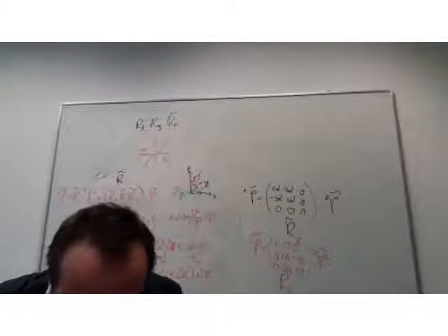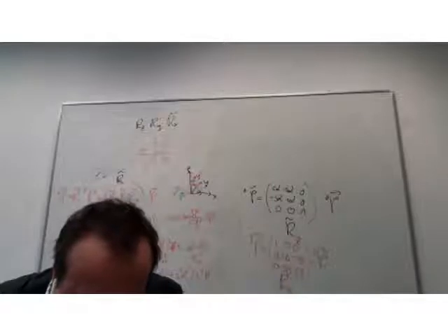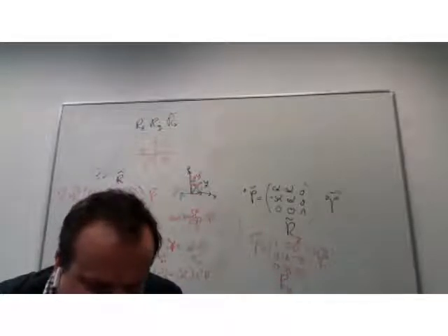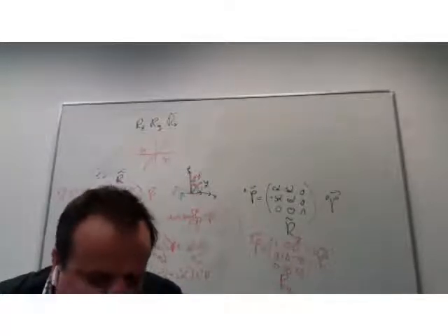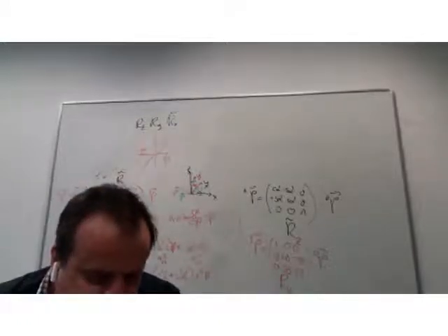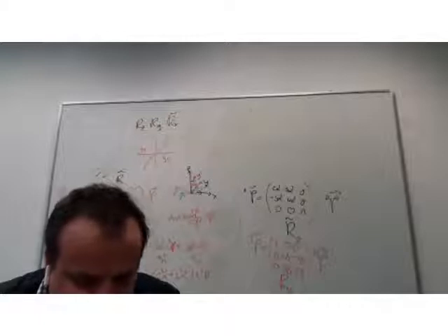We see that, for example, if we divide by cosine beta, the beta value is already known, these 2 arguments, then we have a cosine alpha, sine alpha. Now using the same arcus tangent 2 expression gives us a 0 to 360 degrees value for alpha.